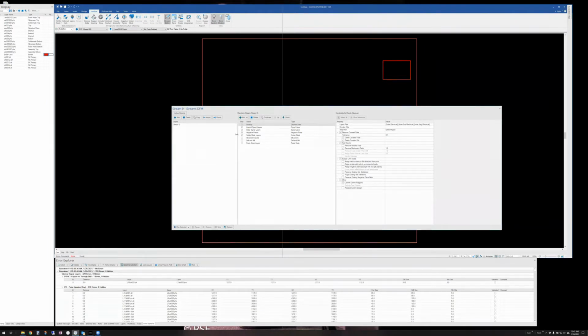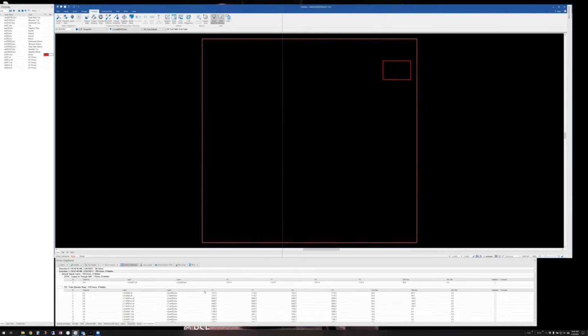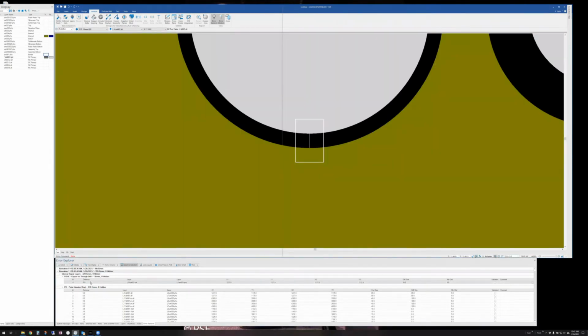When you run analysis, whether it be netlist compare, layer compare, any of these interactive analyses, the streams editor checklist, the results all show in one location now. And that's what this is down here. It was our last tab across here. So this is the Error Explorer. If I want to view a particular error, I can just click on it, and it'll take me right to that error.